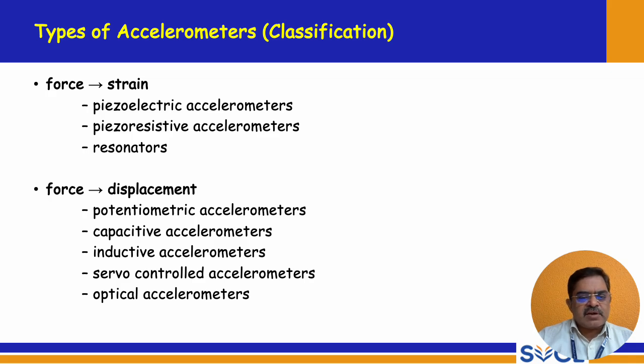So in piezoelectric we know when the force is applied on any piezoelectric material, the EMF is produced, and that force acting on the piezoelectric crystal can be considered as an accelerometer. And in terms of displacement, potentiometric accelerometers, capacitive accelerometers, inductive accelerometers, servo controlled accelerometers, and optical accelerometers. So these are the different types of accelerometers. These are classified under strain as well as under displacement.